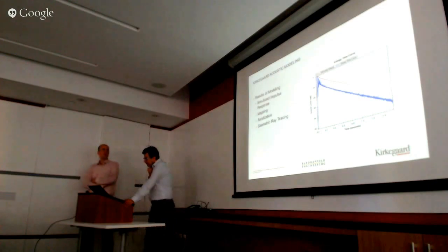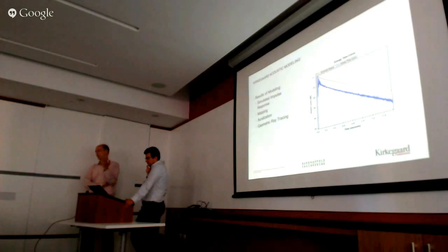So going back, this is just looking at what the outputs are for the modeling methods we have. There's the simulated impulse response over here on the right, and that's basically looking at the timing and strength of various reflections from one source to one receiver point. That allows us to look at it and see when reflections are coming in, if we think that's going to be a problem, and then to try to tweak either the surface location or material to deal with it accordingly.